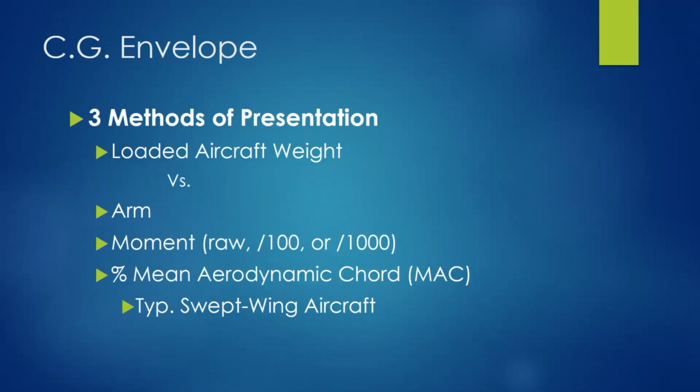If you're right at the takeoff weight, it's a little dicey too. But they build in some cushion when the engineers figure out these loading envelopes. And then we can look at what's the CG arm. Okay, is the CG in the right spot? Or some tables or some graphs look at the moment. They don't even have you divide it.